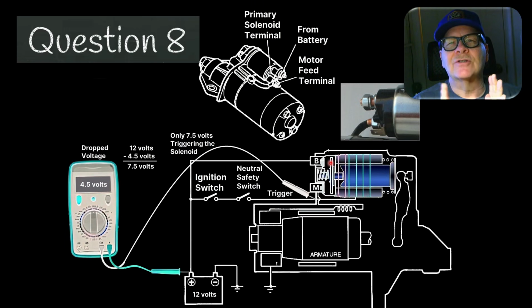So if it goes slowly, it arcs and welds and stuff like that, and it begins to mess up the contacting surface. It starts to drop voltage in here, and then there's not enough voltage, and that low voltage is like a motor trying to run when it's locked up. It's enough to spin it, but not enough to spin it good and strong, and so it burns up starters. I mean, it flat sure does.